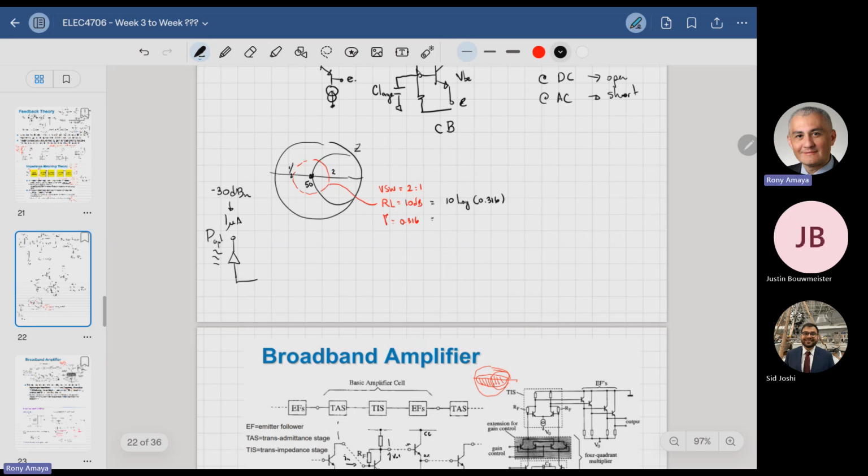because the photodiode has, even though one is in decibels and another is linear, because of the nonlinear characteristics, basically the equivalent of dBms in optical power in are actually converted linearly into actual microamps of current that flow through the photodiode. But you're asking me, where do we use this? Well, that's basically what's coming out of the fiber, and the fiber is hitting it with a power that can be as low as minus 30 dBm.